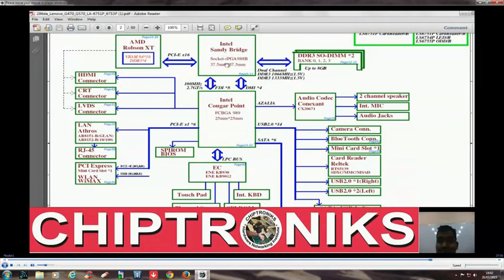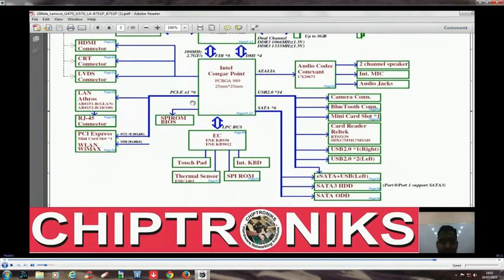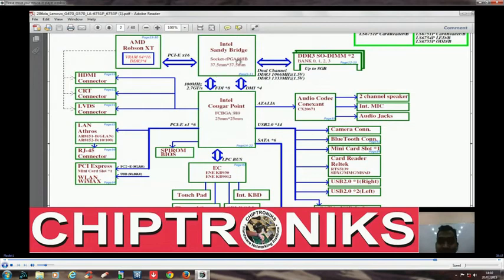So there are two kinds of connection between CPU and PCH. One is FDI, flexible display interface, used only for graphic related data transfer, and the other is DMI, direct media interface. Except for graphic media, the processor will use DMI. That means if the processor wants to interact with the BIOS, SPI ROM BIOS or EC BIOS, the data transfer would take place through this bus, DMI.